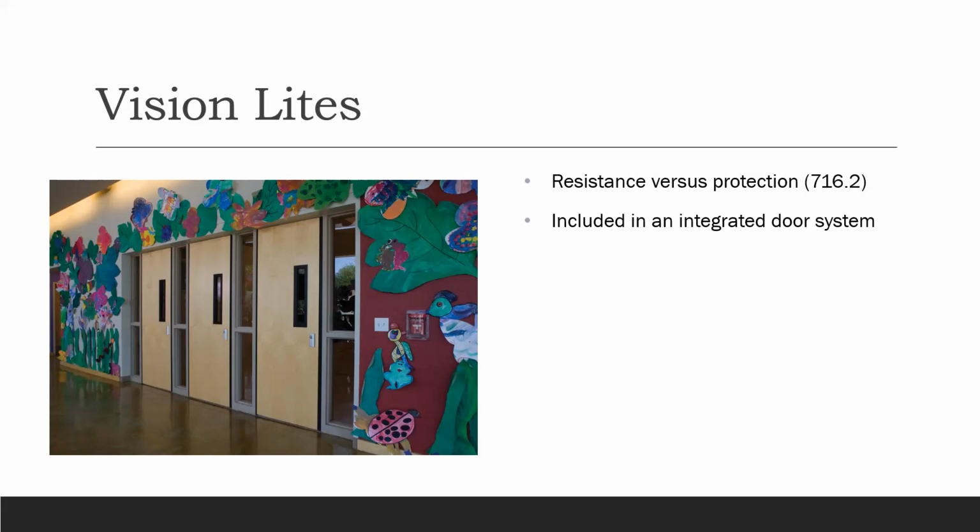It is interesting that this provision can be a bit tricky, because I would think most intuitively we would put light kits typically on the latch side. That's where we usually would see them. But sometimes, because of that first quarter opening provision, we might see a light kit actually on the hinge side, which is kind of interesting.